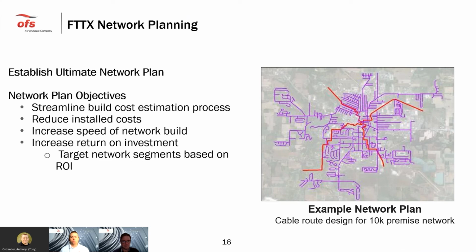Next, it will also help reduce the installation cost. If you've got areas that can potentially go aerial versus buried, or different types of architecture that can be deployed, potentially one being more cost effective than the other, those are things you need to identify up front so that you've got the most efficient and cost effective network possible.